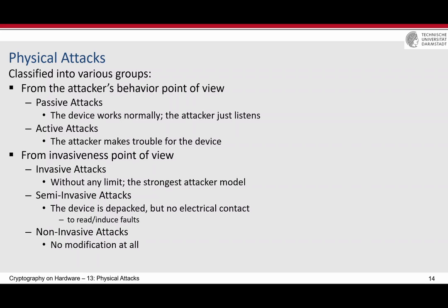From another point of view, we have invasive, semi-invasive, and non-invasive attacks. Non-invasive attacks mean that the device is as it is. We don't make any modification on the device or its package. In a semi-invasive attack, you can depackage the device, because the device has a package, a plastic package or ceramic package or some form of metal package or cover.